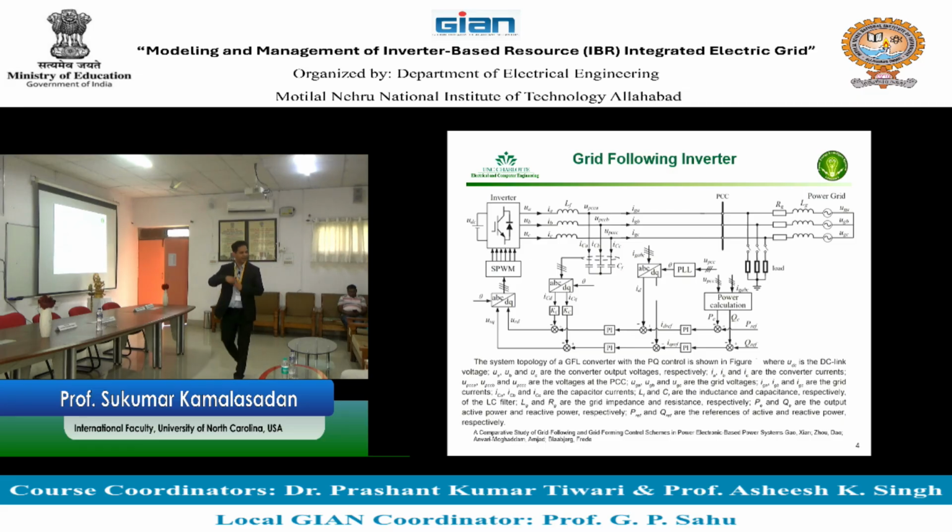When the electric grid is not there, we have a challenge. You need to generate this angle by ourselves. That angle is not coming from the electric grid. Oh, we have another challenge. This voltage, which is stabilized by the electric grid, will start going down. So you need to lift that voltage magnitude to a constant value and also generate our own angle. Such inverters that do that job of getting the voltage and angle are called grid forming inverters.